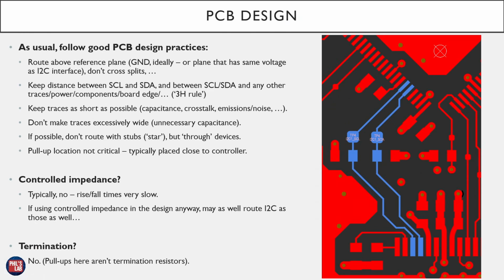Lastly, looking at PCB design, and we'll go through some real-world examples as well. I2C, as you saw from a schematic point of view, is very, very straightforward, and it almost seems like it's even more straightforward from a PCB design point of view. Again, it's a fairly low rise and low fall time interface, so it's fairly forgiving. All we have to do, as usual, is follow good PCB design practices.